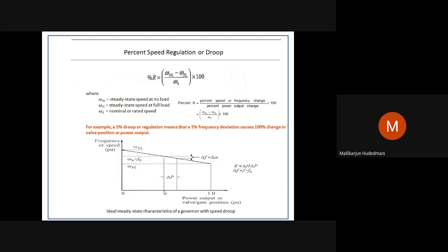For that requirement, we are trying to understand basically the response of a governor to a certain change in load. We call it droop characteristics. To understand that, this curve helps us. On this curve, the important things are no load speed or frequency, full load speed or frequency, and set frequency or operating frequency. From that curve, if I take the slope, that slope represents the regulation of that machine. Then we will come back over here.